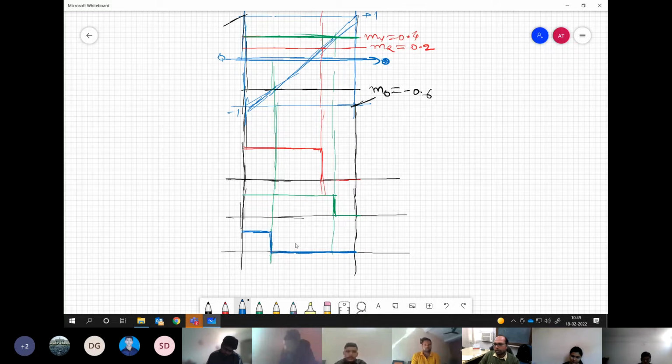If it is 50%, then it will exactly match 50% on and off. Now this is the gate for R, then gate for Y and gate for B. You understand this point? This is how the gating signals will be given for the top IGBT. For the bottom, it will be just the opposite, with consideration of dead time and other things.